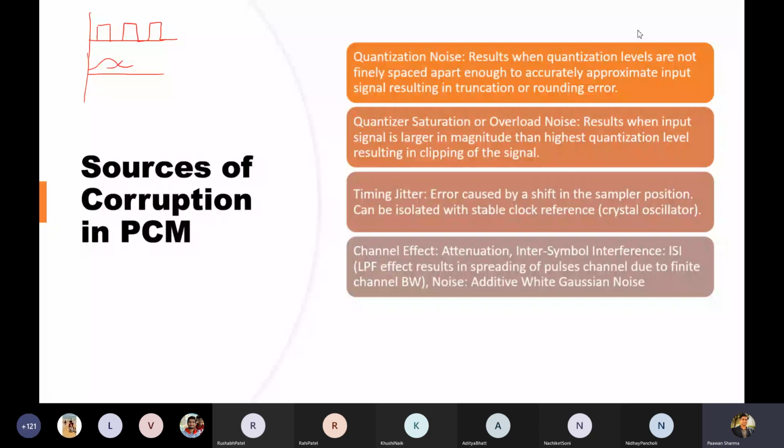So you can see the overall signal will be like this. So it is a kind of pulse broadening, and this signal might interfere with the 0 bit at this point, which is not good. So that is what we call inter-symbol interference.